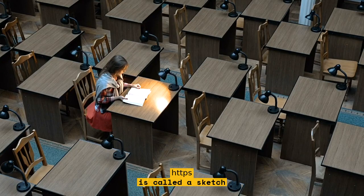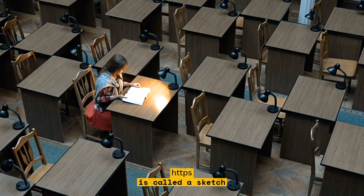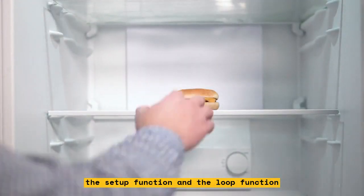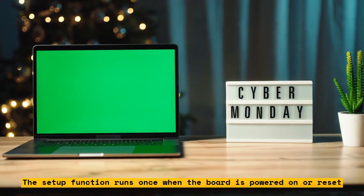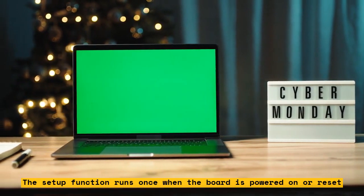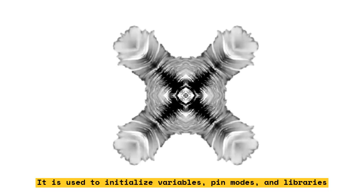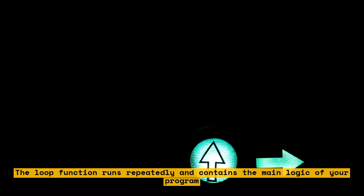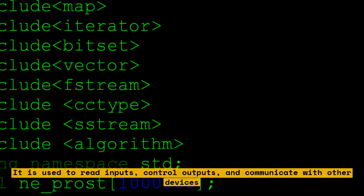A sketch consists of two main parts: the setup function and the loop function. The setup function runs once when the board is powered on or reset. It is used to initialize variables, pin modes, and libraries. The loop function runs repeatedly and contains the main logic of your program. It is used to read inputs, control outputs, and communicate with other devices.